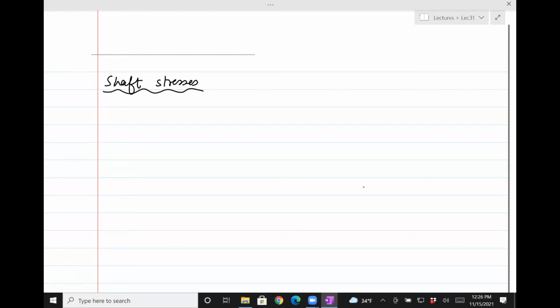No, because the place where the bending moment is maximum doesn't correspond to the place where the shear force is maximum. Right? I thought where the bending moment diagram goes to zero, that's where the shear force is. Yeah, but that's not always true. Let me correct myself. That's true to an extent, but there were some problems in the homeworks where there were at least 2 points where the shear force and bending moment were important to be considered.